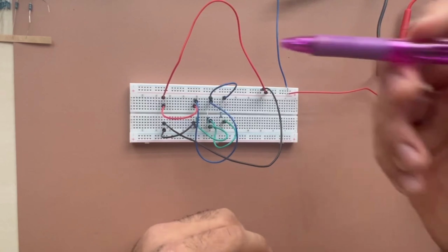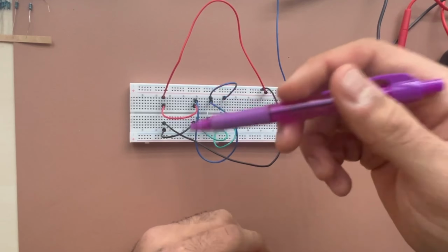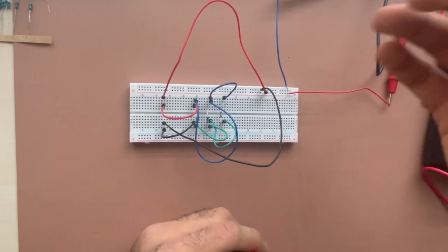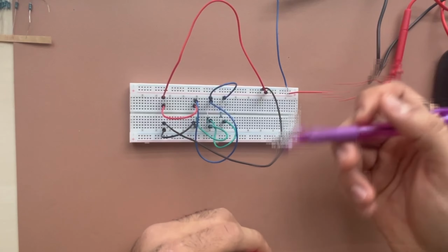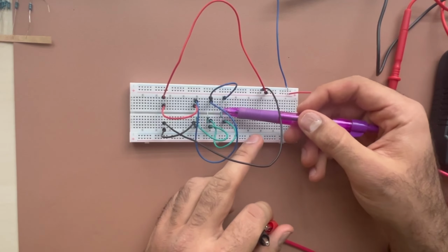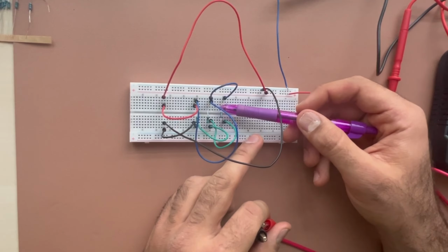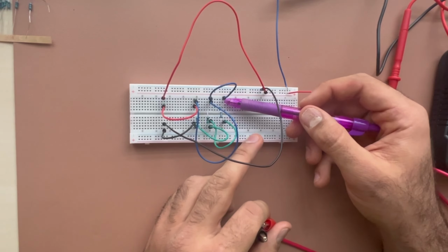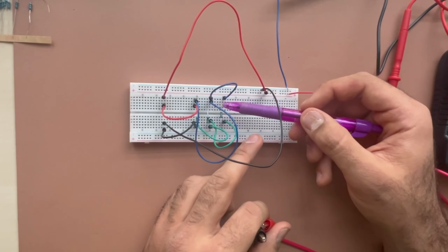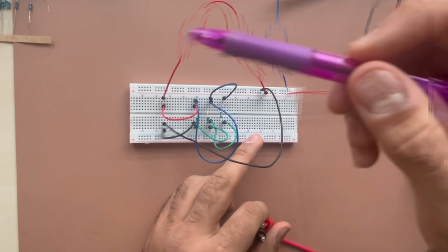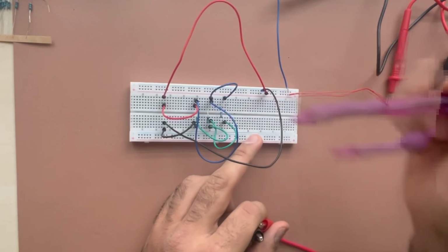When you connect our ammeter, it should be in series. It should be in the way so that it doesn't have any effect over the other side. So the only thing I have to do, for instance, if I talk about the 10K, is disconnect this part and disconnect this section. The current, instead of going to this guy directly, first moves through the ammeter, then goes through that.